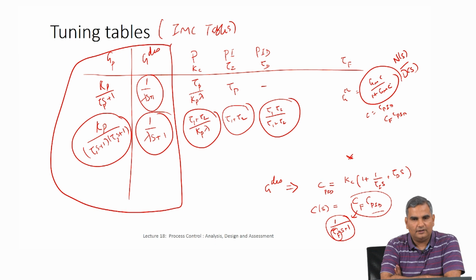And once you have these model equations, we got to what is called a state space form of these model equations, where I have states which, as far as this course is concerned, are differential states on the left hand side. So I get equations of the form dx1 by dt equal to a function of states and some inputs, and dx2 by dt a function of states and inputs. Then we showed how you can linearize these state space equations to get linear state space equations.